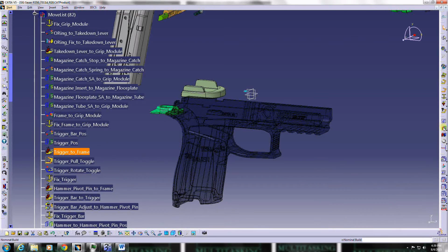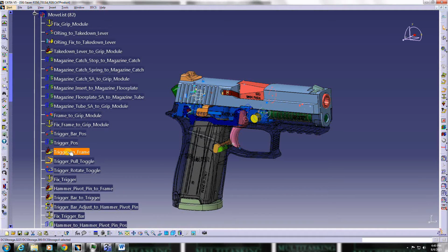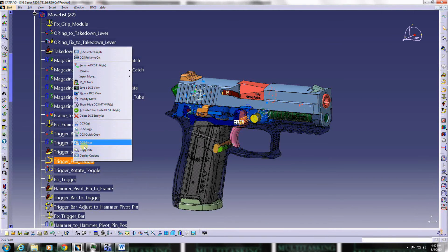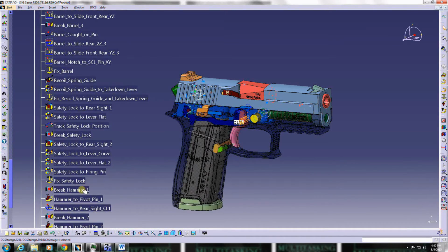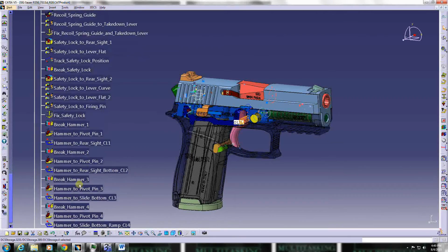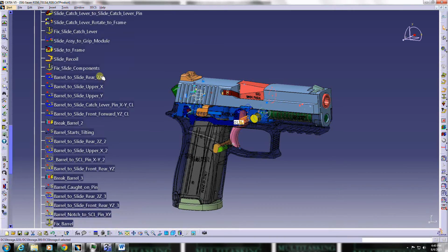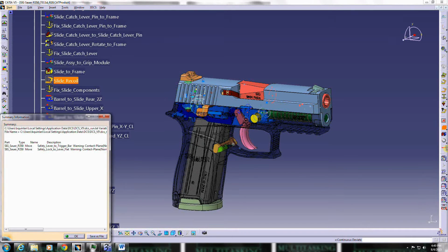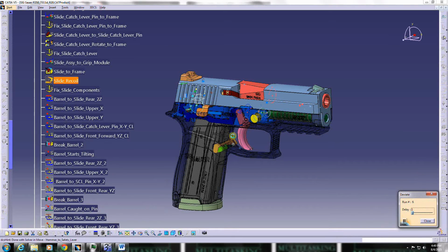As it's saved, the trigger's already pulled back. You can turn off the trigger rotate move, turn on the trigger motion move, and then turn off the sliding move. There you go. Now it's going to show you the motion when the trigger moves.